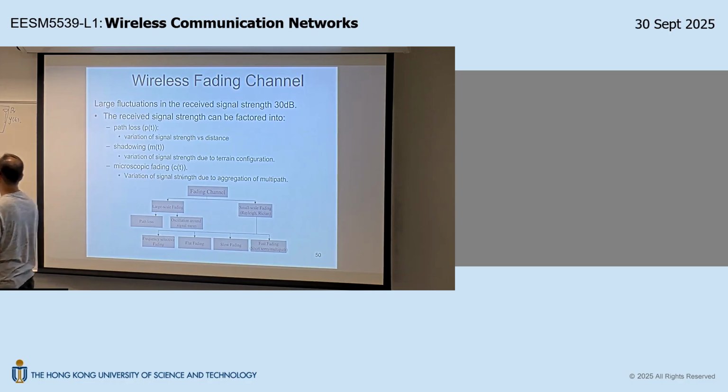But now, the first thing we need to check is whether this is an LTI system, right? Whether this is linear and time invariant. So first of all, is it linear? To judge whether this is linear, you need to go to the physics. So what would be your judgment? Is it linear in this propagation channel? It's linear, right? Because the foundation of this is the Maxwell equations. As I mentioned, the differential operators in the Maxwell equations are linear operators mathematically. So therefore, the propagation itself is a linear process. Okay, so this is linear.